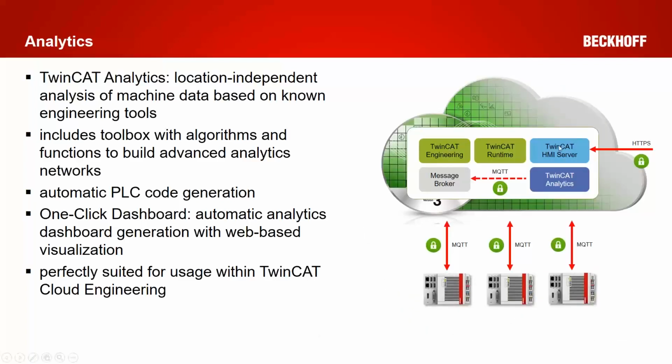So this is what you see here. We have added a TwinCAT Analytics module here that is getting the data via MQTT from the message broker. Again, data coming in from different physical controllers that are publishing their data. Then you can analyze the data within TwinCAT Analytics. And then you can actually use the one-click dashboard functionality of TwinCAT Analytics to automatically create a TwinCAT HMI project so that you have a visualization within a few mouse clicks.